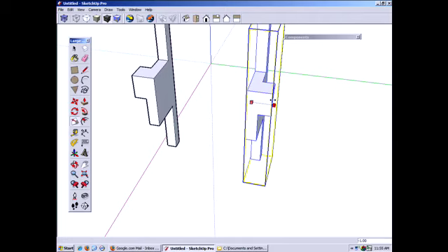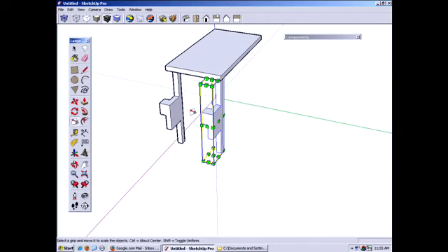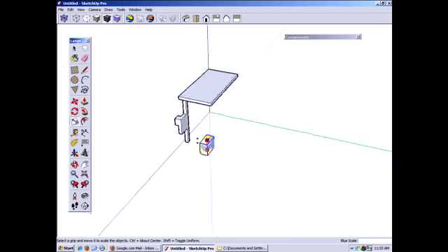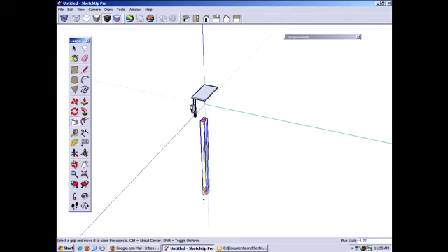You can mirror things with the scale tool just by understanding which direction you want to mirror this in. If I wanted to mirror it vertically, I'd grab the middle grip from the top or bottom and mirror it vertically, right? And I can stretch it far down and just type in -1 to get a negative 100%, or it's a mirror.